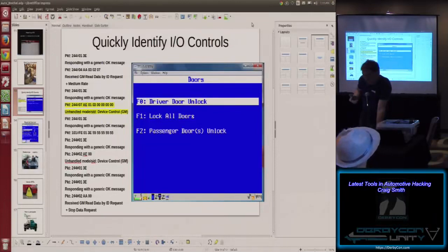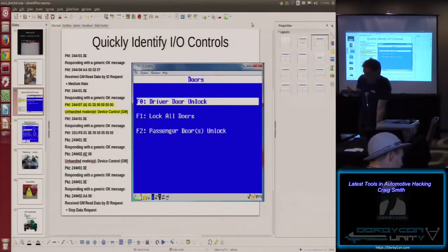One thing to look for with these keys is you can make a request for the seed, then scan the memory space to see if you can see that seed show up in memory. If you do, a lot of times these embedded systems will also pre-generate the response it's supposed to be, and it's usually stored right next to the seed. So you can then make a request, and once you know the memory region, pull off the memory, check the bytes next to it, and then send that as your answer. It's usually within the right amount of time to do it, and it can be a pretty smooth way of unlocking that without having to deal with any of the guessing of the keys or anything of that nature.